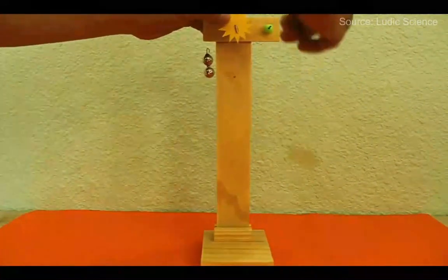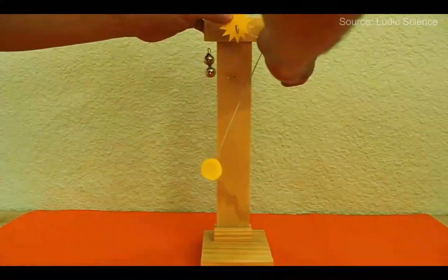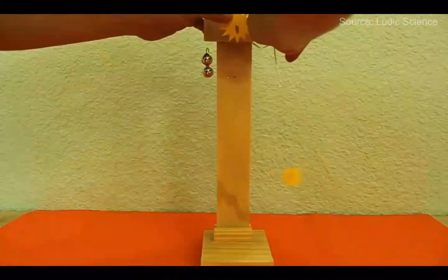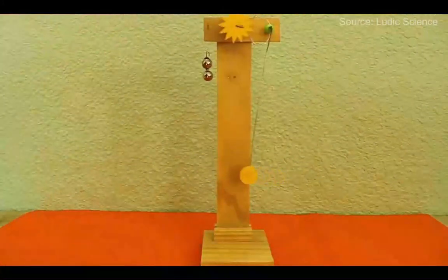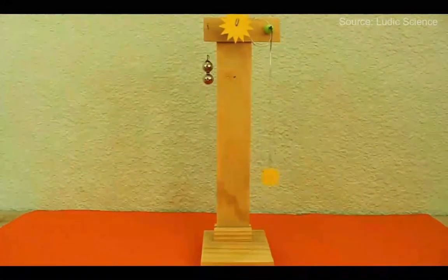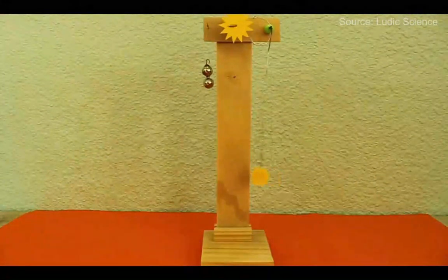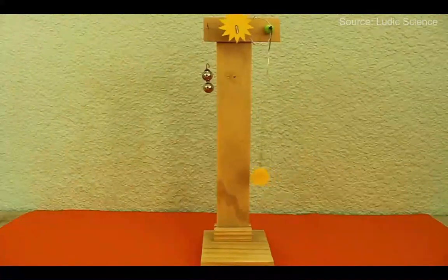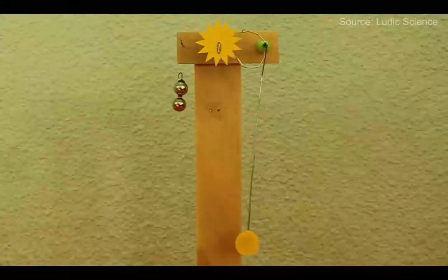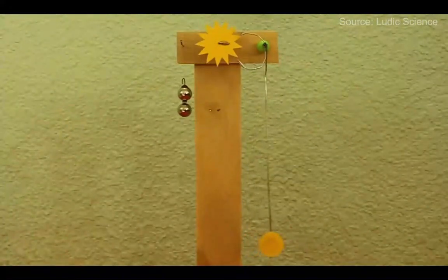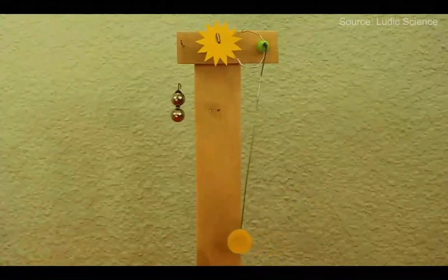The way this works is, the weight coils around an axle behind a gear, such that when it falls, it unwinds and rotates the gear, sort of like a spinning top. The escapement mechanism of the pendulum prevents the weight from just whizzing down and instead acts like a valve to slowly channel energy into the pendulum by giving it a nudge every rotation, which keeps the pendulum swinging.